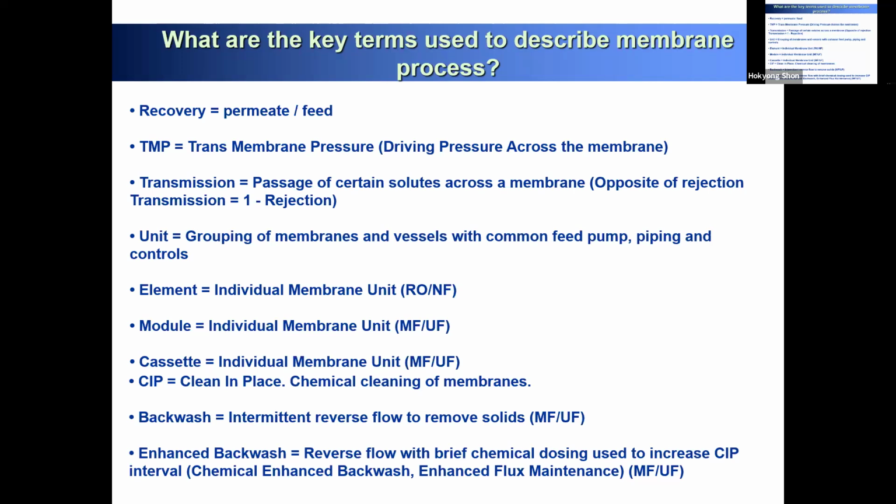CIP is cleaning. So when you operate for 1 day, 2 days, you have more organics attached on the membrane or some inorganic scaling. So you need to clean up: acidic cleaning, base cleaning, or flushing the water will give a good cleaning to produce more water flux.